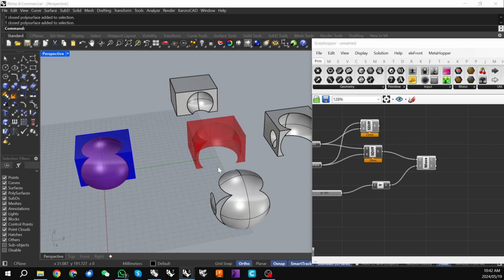So if there's no other paradigm that you would use Grasshopper for as a product designer, I'd highly encourage you just to use it for what I'm using here, just as the ability to do sort of Boolean type operations, but with live previews and the ability to do sort of fast iteration on your objects. So that's my hello world.